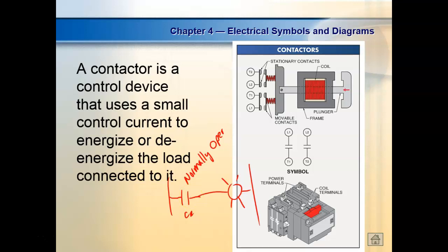So what this symbol means is that if I came over here, this was L1, and then I had this controlled by a relay, and then I had a light over here. Then the position it's in right now, this contact would be closed and the light would be off. I come over here and put power on the solenoid. It causes these things to shift. So this would move down here. My circuit would be wired between here and here, right? You'll understand that. So now the contact's closed and the light will come on. And these are called normally open contacts.